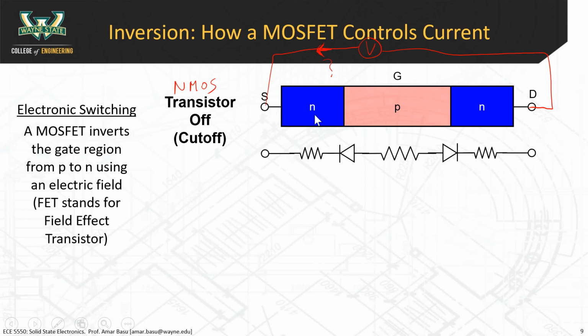If you look at the N-type semiconductor, we know that the N-type semiconductor behaves as a resistor. That was chapter 3. We know from last chapter, chapter 5, that wherever there's an interface between a P and an N-type material, that is a diode, and that's denoted by this diode symbol. So in the P-type material, you have a resistance here, then another diode here, and then another resistor here as you go through the N-type material.